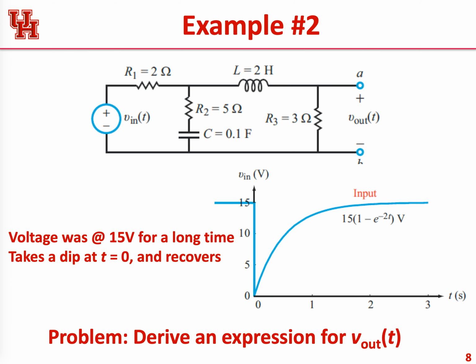So let's go back and look at our original circuit. In the original circuit, we had a voltage source, Vn of t. We're going to find the Laplace transform of the input voltage, so this is going to become capital Vn of S.